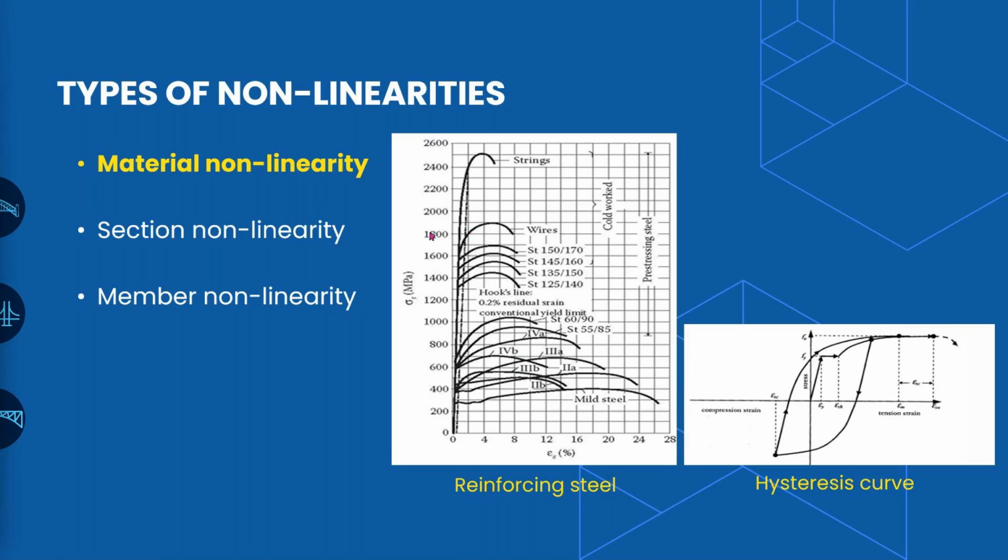So it is not that if we are using higher strength steel, we are making stronger structures or stronger bridges. Many of the codes also give a certain limitation on the strength of the structural steel that is to be used in the bridge, so that the ductility of the structure is not compromised.